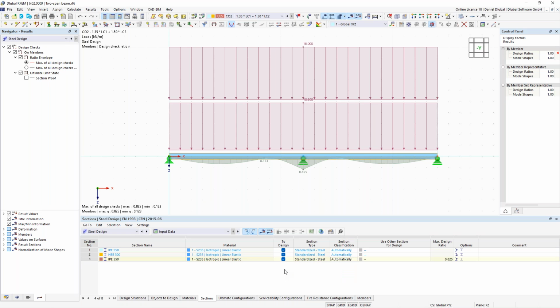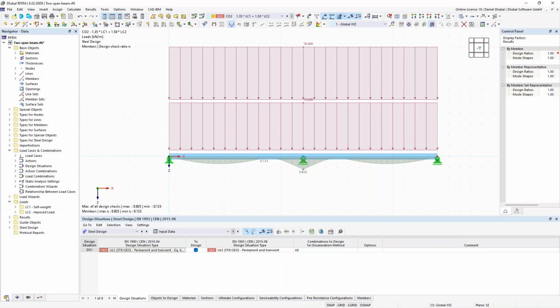So normally in the study, I perform some basic elastic stress designs. So now I want this also to consider here in RFEM. Now I have several possibilities, and I would like to show you one. On the left side of the data navigator, when activating the add-on steel design, you find two additional folders, I would say. We have on the left side types for the steel design. This will be important when we perform another example: effective lengths, boundary conditions, and so on.